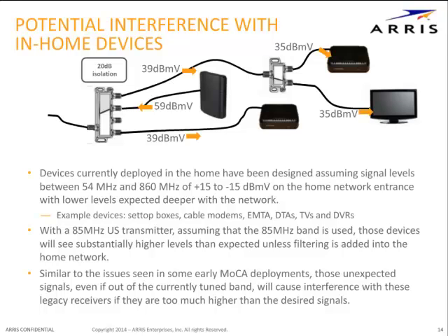When the modem is transmitting at that level, heading back upstream, you always have crosstalk or reflections within the in-home splitters. And as an example here, I've shown a splitter with 20 dB isolation. You may have better splitters. You may have the occasional splitter that doesn't quite meet this either. But just for the purposes of illustration, you can see that because of the inherent crosstalk within the splitter, you're going to have high levels traveling back to the other devices in the home.